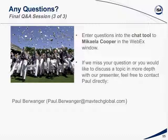Now, having said that, it tends to be kind of the same in practice, with the distribution. But once again, don't get hung up on the distribution. If you properly prioritize these alarms during the rationalization, just let the engineering speak for itself. You may have a distribution that looks different than that. I've been at a couple of facilities, because of the nature of their processes, that looked significantly different than that, but it was the correct distribution for that facility. And we were all agreed on that because of the highly hazardous nature of some of the materials they were dealing with.